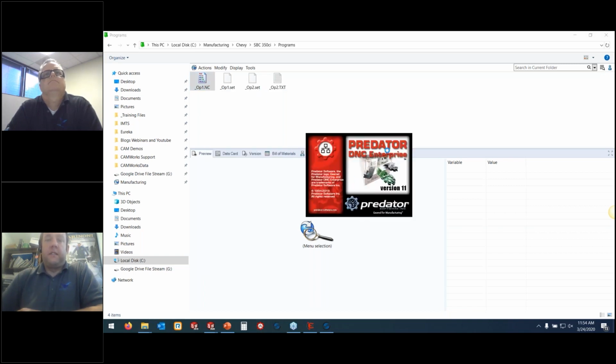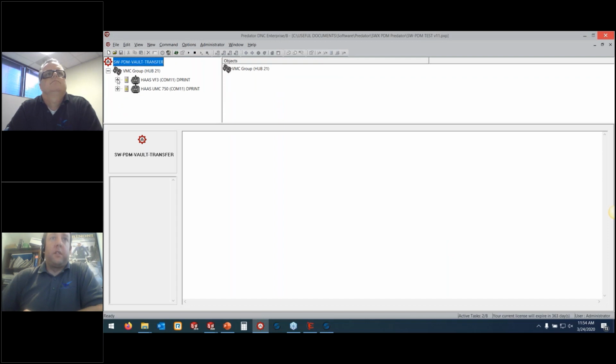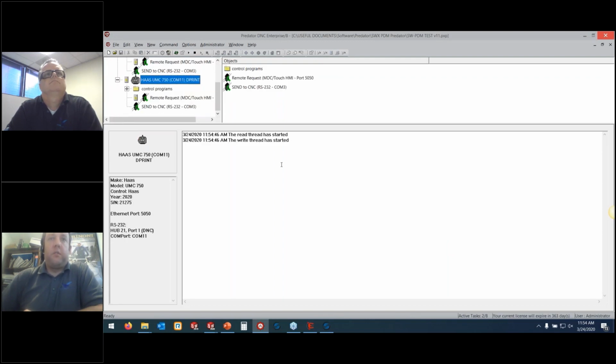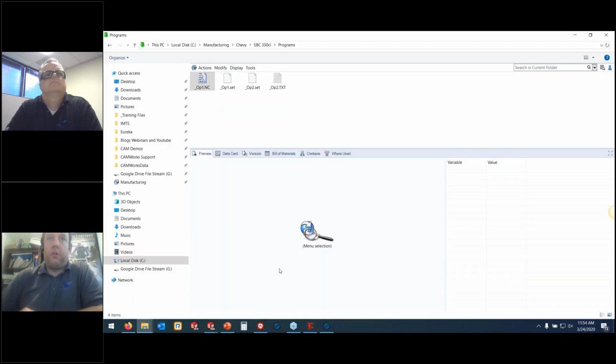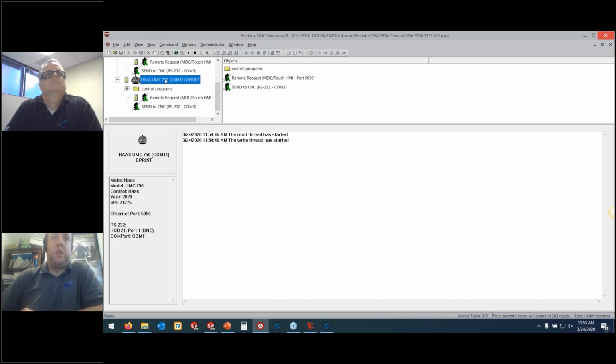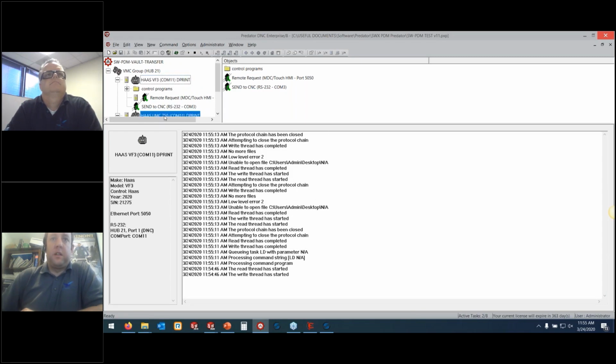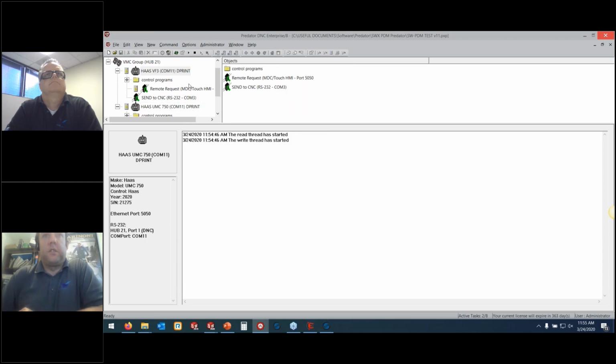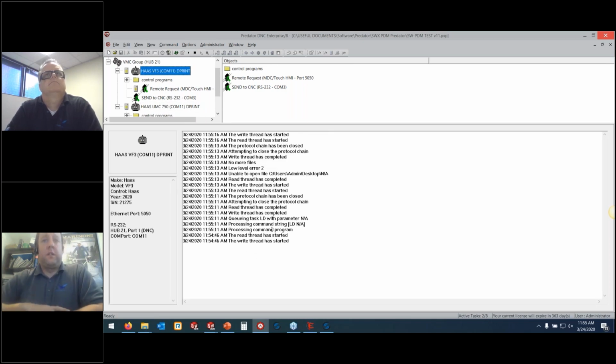So I can actually use Predator DNC to communicate to the CNCs right from PDM. In here, I've got my machines listed. So I can click on my machine here. It's ready to receive the code. I can check on all that. But I can actually go to my program right here and say op1, send to CNC, Haas, UMC 750. So that is actually going to read the data into my machine program and push it right over here. You can see it reading the data into my programs. Looks like I probably sent it to the wrong one, but this is actually sending that code straight to the CNC. So it'll be ready right out there for you, Tim.